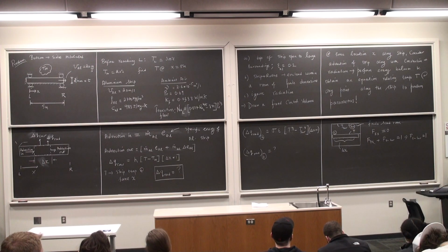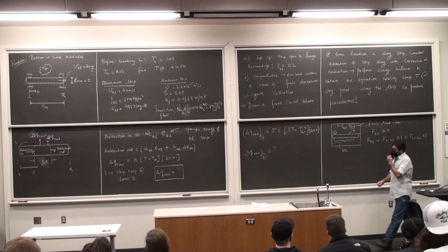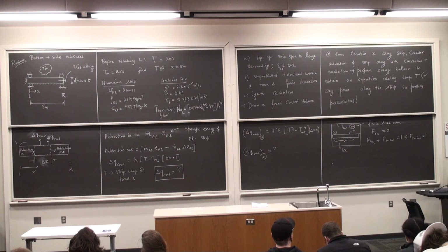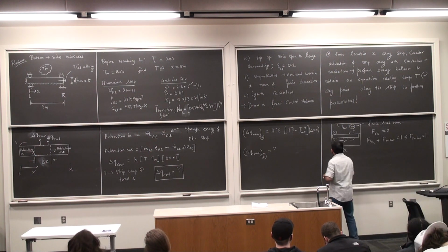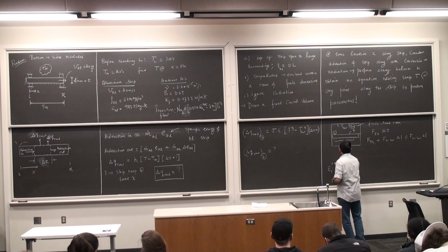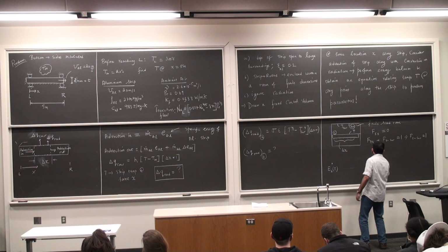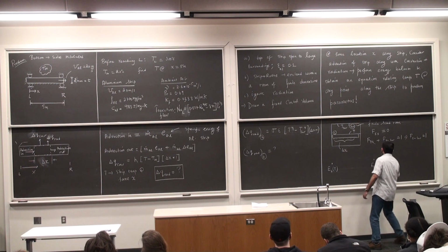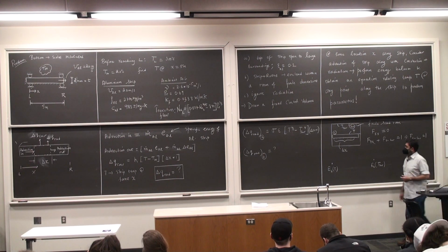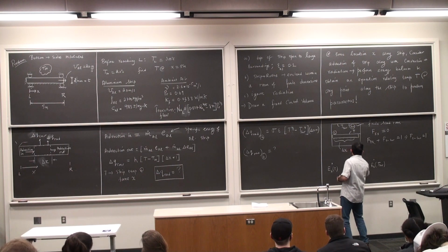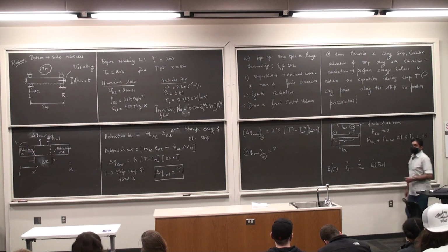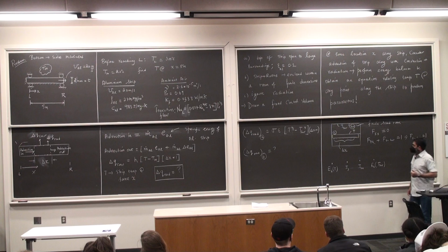And how to find delta Q radiation is by drawing the resistor network. So in this case, we start off with the fundamental nodes, which is the temperature of the surrounding and then the temperature of the strip. So here is E_b at T, T surrounding, this is the emissive power of the ideal body, which is at the same temperature as T and T surrounding. Then I have the radiosities, J surface, J surrounding, join them all together by the resistances.